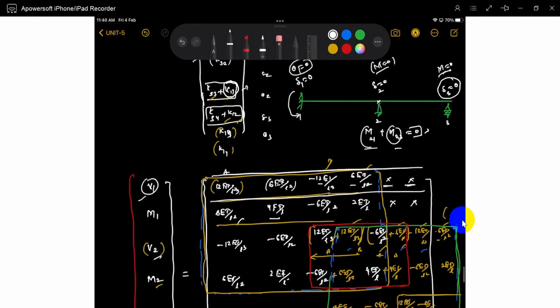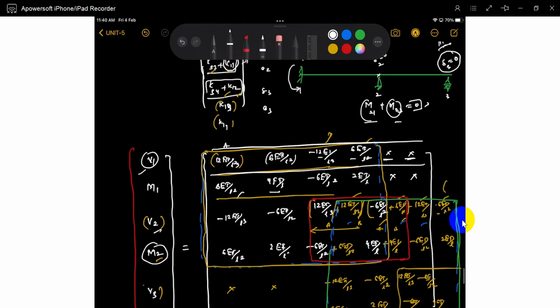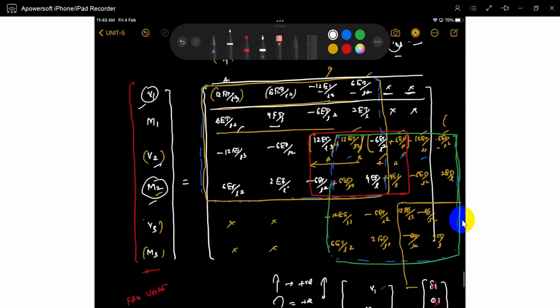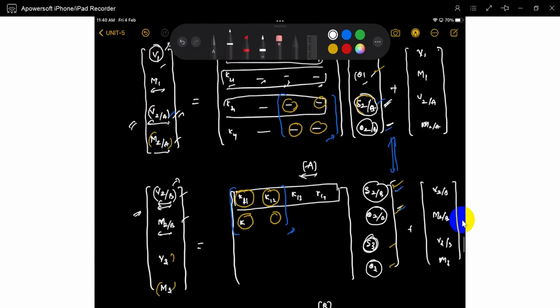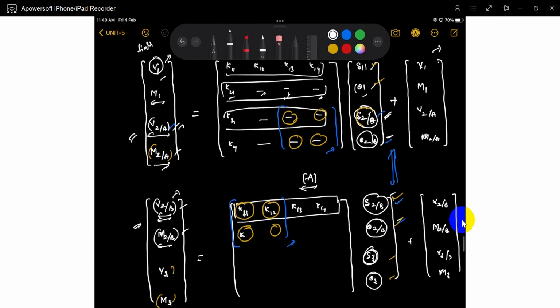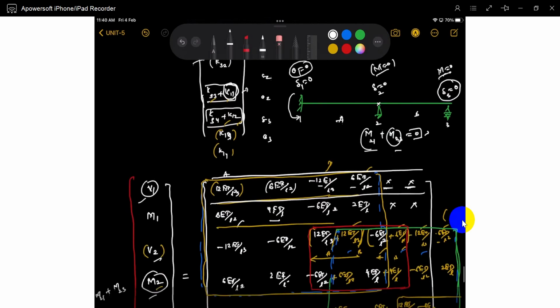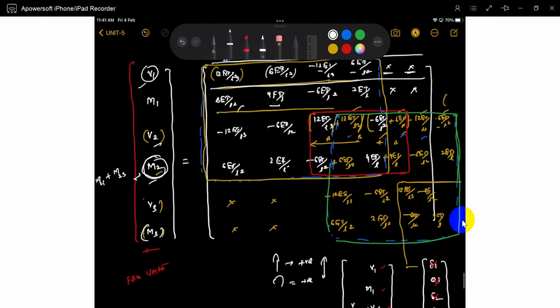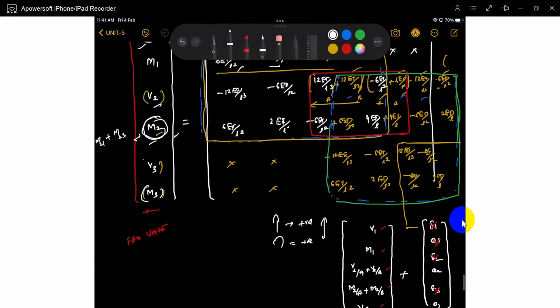So that's why here, see M21 and M23. Here you just add these two. Here M2 means what? For the A element and the B element, you just add the final moments. M2 is M21 plus M23. You already know it. Previously we saw here M2 for the A element, M21, and here M2 for the B element, this is M23. You add them. So these values are zeros. This is 0, this is also 0.